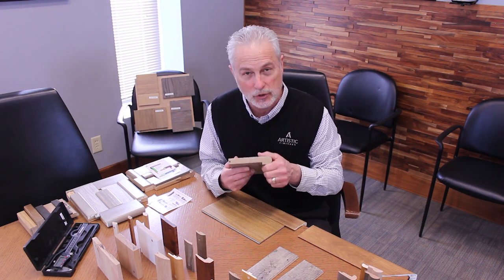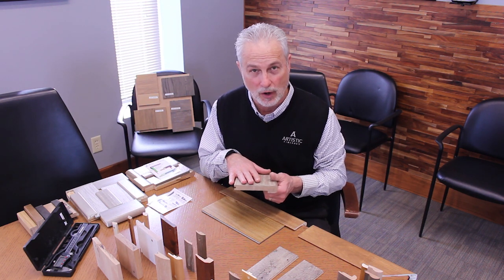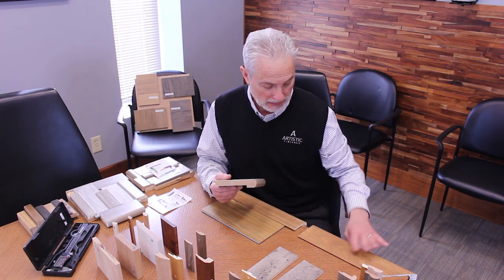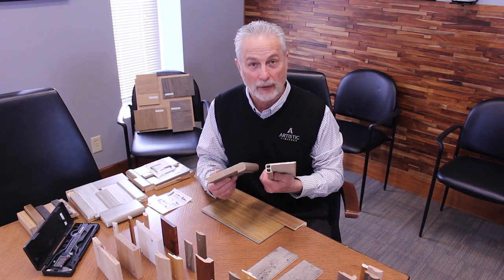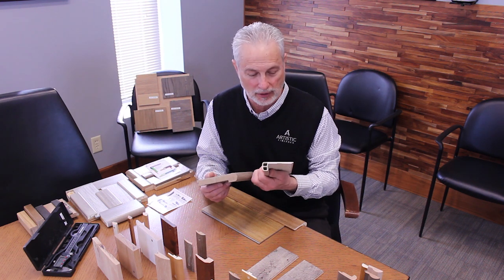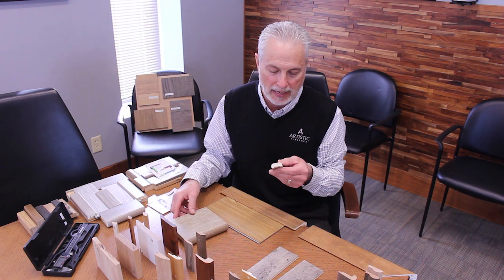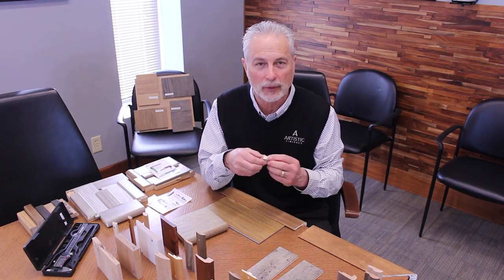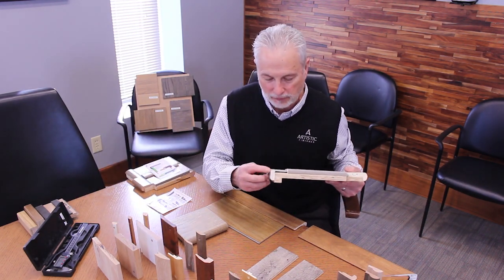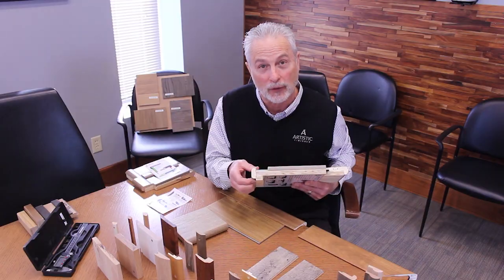Very critical to distinguish the bullnose separate from the face and the majority surface-wise of a stair nosing. The bullnosing can range from being full radius to having a square-edged of various radius size, this being about a 6mm radius on a square edge front, all the way to some of our adjustable minis in stair nosings that now range up to about an 8mm radius and can be used on surfaces similar in the multi-layer flooring categories for floors of different heights. This just happens to be about an 8mm floor where you can vertically mount those.